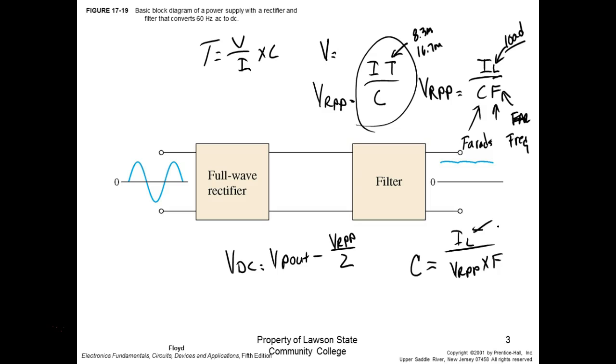So you might get a 100 microfarad capacitor that's like this, and it's rated at 25 volts. And you might get the same capacitor at 100 microfarads, and it's that big, and it's rated at 200 volts, right? Understand? So they have to get the plates further apart. Are we okay? Lost anybody so far?